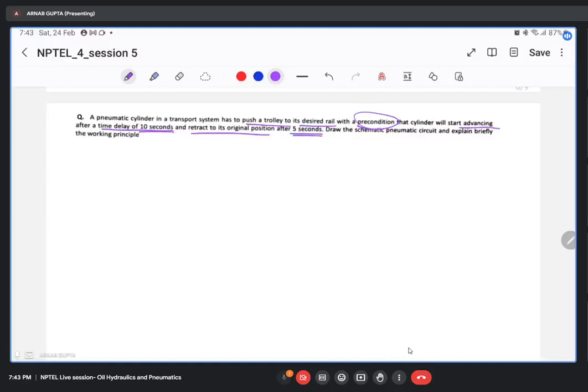As soon as you see this word or term time delay, what should come to your mind? That you should be using some sort of delay valve, time delay valve. Okay, so we'll see how it can be done. Draw the schematic pneumatic circuit and explain briefly.